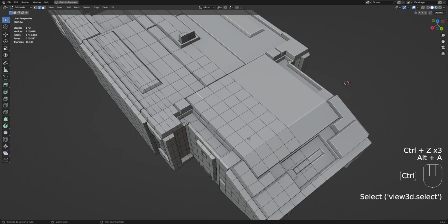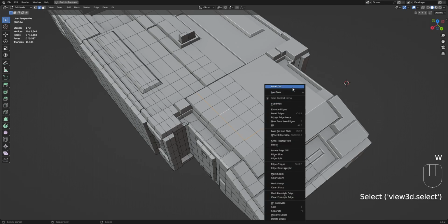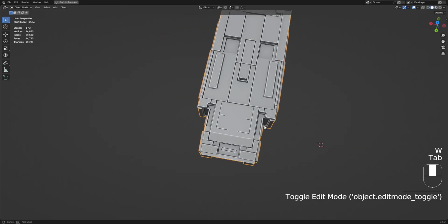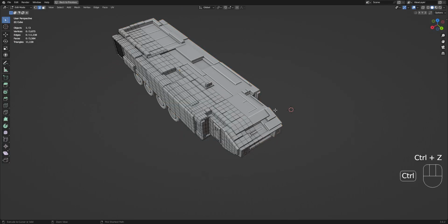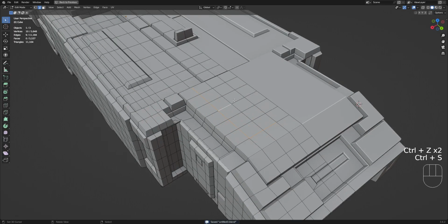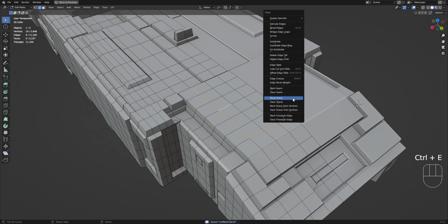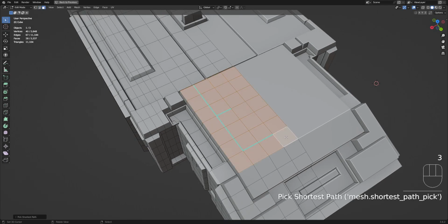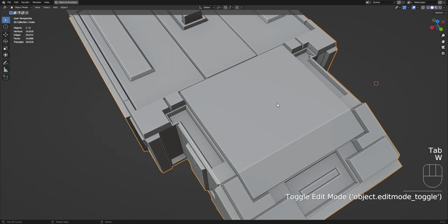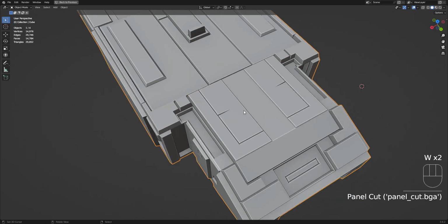The edges you select don't even have to be contiguous. It can even be just like that. For the inset type, this needs to be contiguous, of course. And if you use this on this type of topology, with this marked sharp edge here ending abruptly without touching the end of the selection or another edge that is marked sharp, you can see the result. And I'll cut inset. There you go.